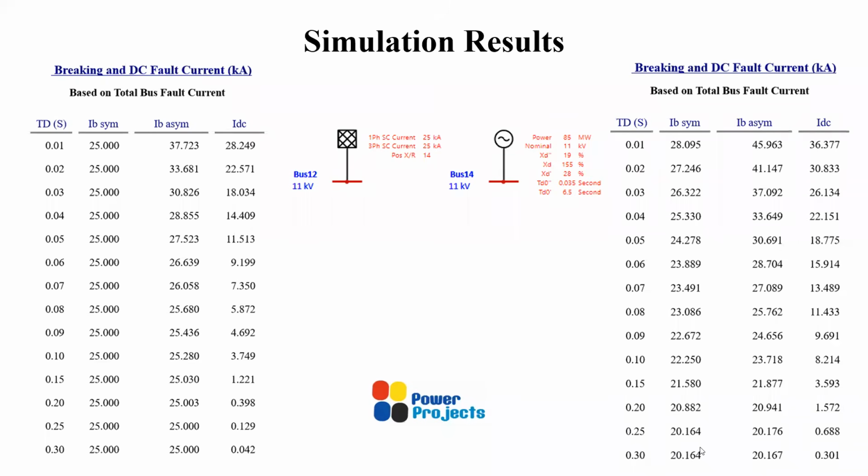to 20. Which means when you're working in islanded systems, which are not connected to the grid, where only a few generators are there, then the fault current will not be stable. The fault current will come down with respect to time. So when you're coordinating your relays, you need to ensure that the reduction in the current because of the change in impedance of the generator also has to be accounted.